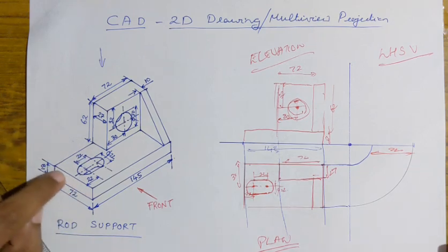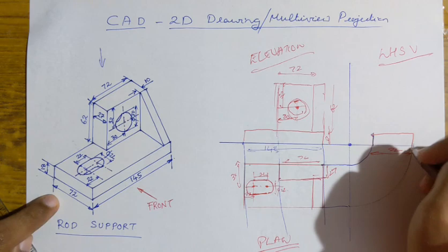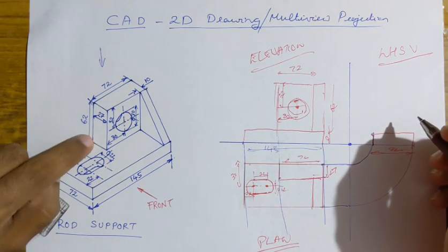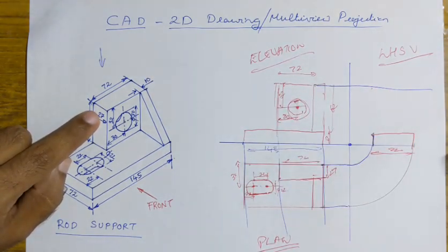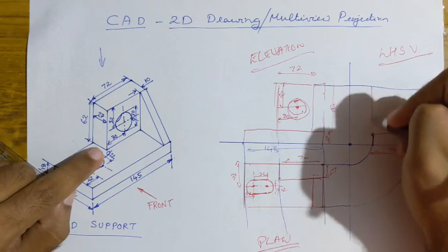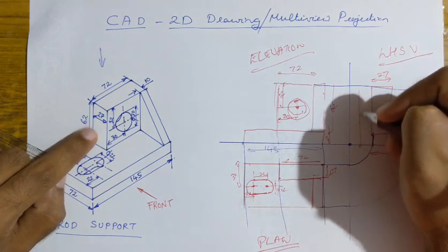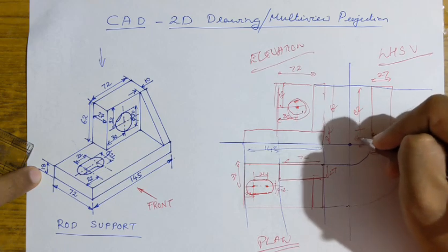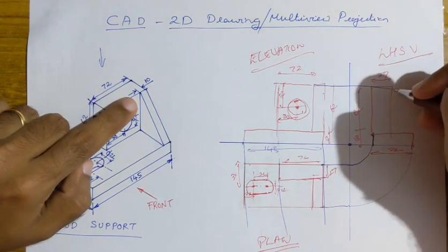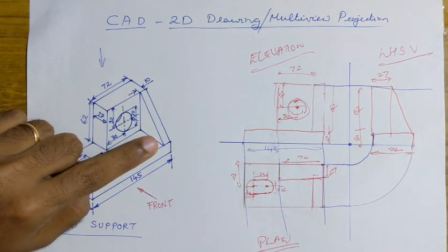You have the rectangular slab at the bottom. After that you have this rectangular face. Just extend this projector. So you have this rectangular face. The width, as you all know, is 27. This total height is 62 plus 18. So this is 62, this is 18, this height we know, and finally you just have to complete this triangular rib. So that is about the side view.